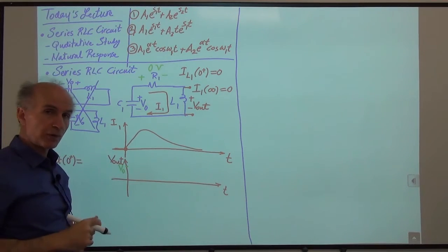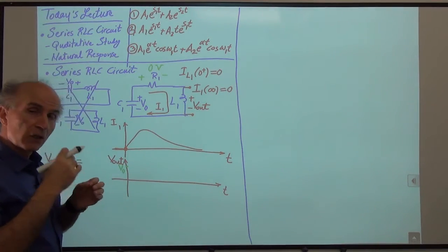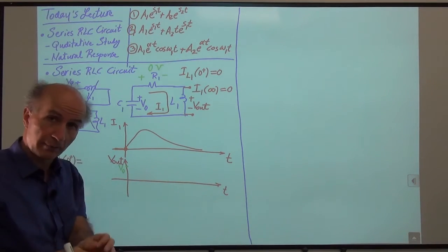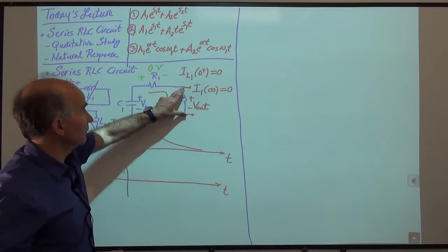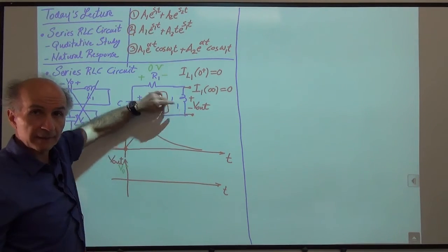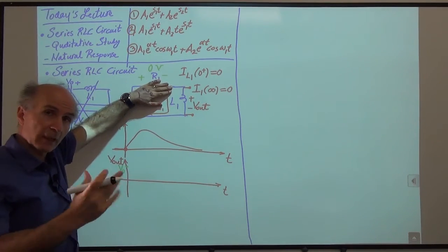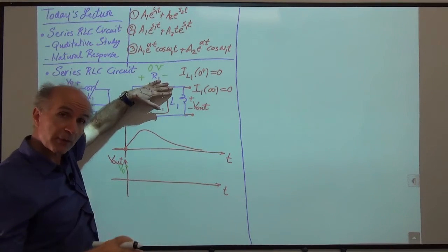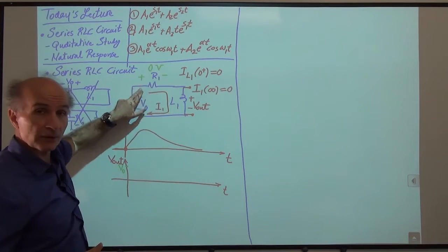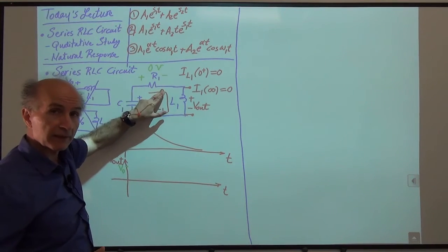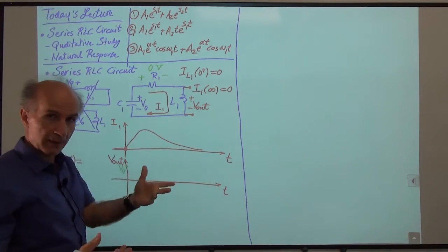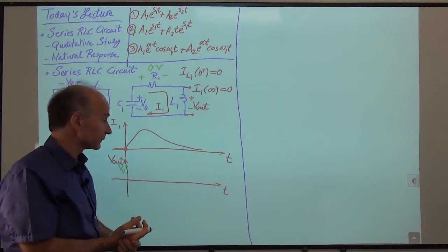All right? So you see we are following a logical thought sequence based on all the fundamentals that we are sure about. If I had tried to figure out this voltage at time 0 plus based on this inductor only, it would not have been easy, right? Okay, how much is the voltage here? I don't know. L1, what is it doing? Is it open circuit? What is it, right? But by utilizing this resistor and finding the voltage on it, and then deciding that this voltage and this voltage have to differ by only this much, we can see that V out is equal to V0.